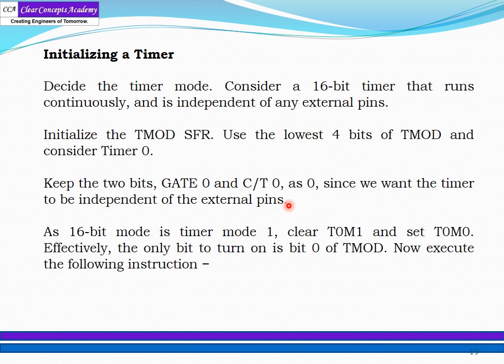A 16-bit mode is timer mode 1. Clear T0M1 and set T0M0. That means you set 01, so you are now setting it to mode 1. The only bit to turn on is bit 0 of TMOD. Now execute the following instruction.